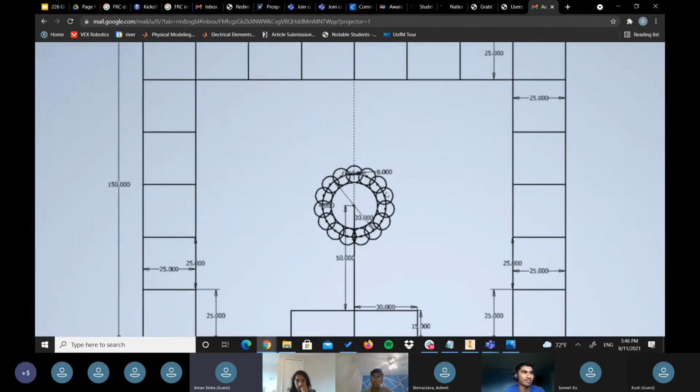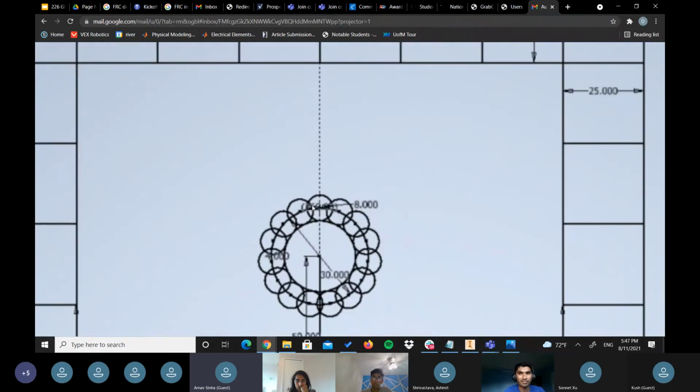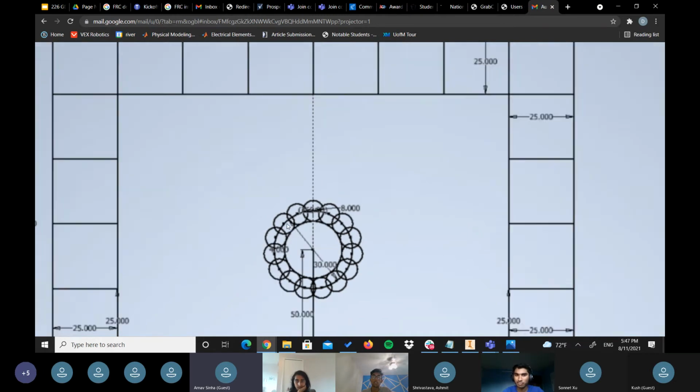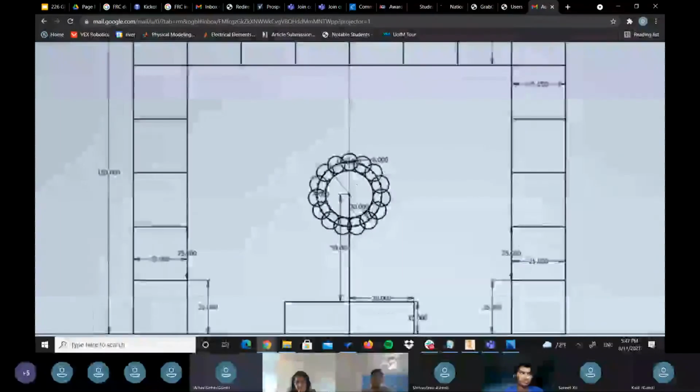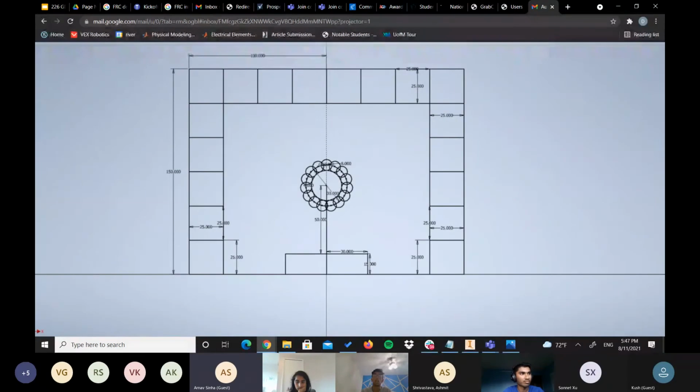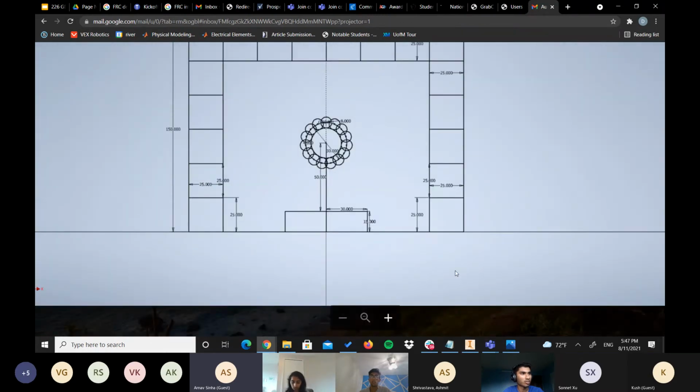You see there's a circle going through the centers of the circular pattern. Did you select that for what it's following? Because that's not actually part of your drawing, you're just using it as a reference, right? I would select that, and on top, I don't know if it's in the picture, but we went over the construction tool. Because it's not part of your actual drawing, you should select that and click construction. So it will come as a dash line. But yeah, everything else seems pretty good. Okay, thanks.